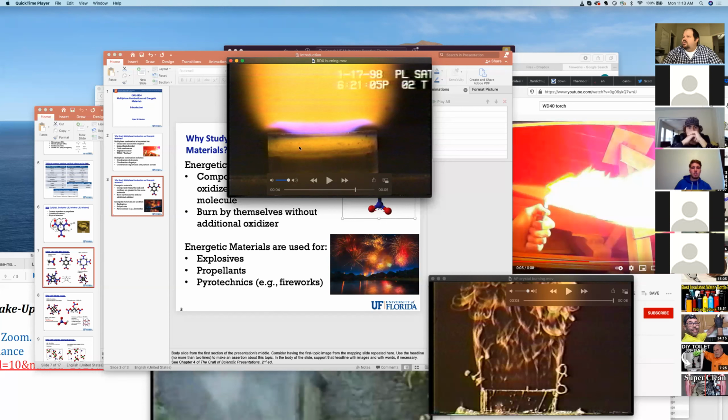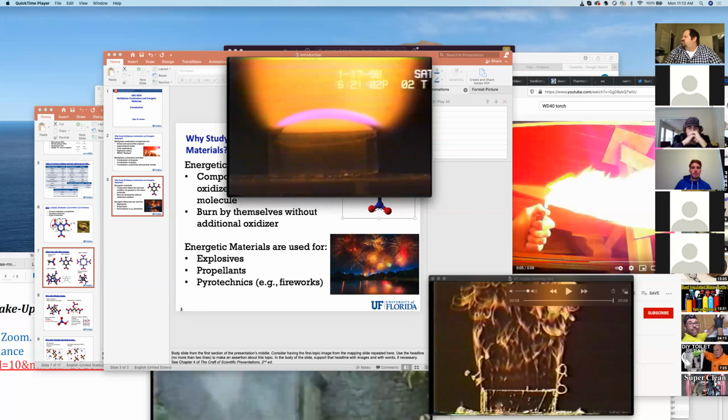And between here and the flame, you actually have what's called a foam layer. If the movie plays cleanly, you'll see all these little bubbles and things like that. And so the structure, not only in the flame on the gas phase side where the actual chemical reactions are occurring, but also within the solid itself, there are really complex phase change processes, bubble formation, things like that. So it's really, really complicated, but that's what makes it interesting.